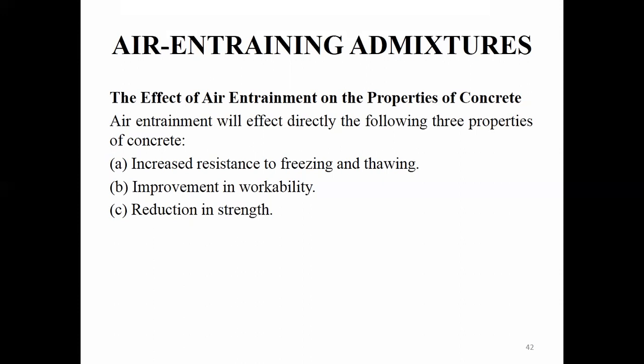And also the concrete containing this entrained air is more plastic, so it does not stand stiff. That is why the slump value of this air entrained concrete is a little higher than the conventional concrete, right? So the entrained concrete is more plastic, so it can be easily handled when compared to ordinary concrete.